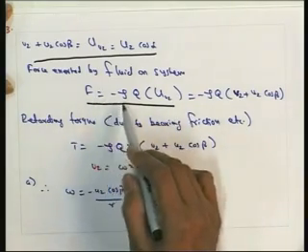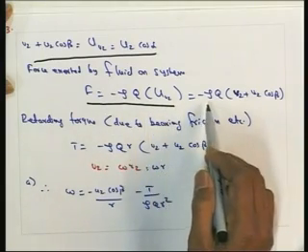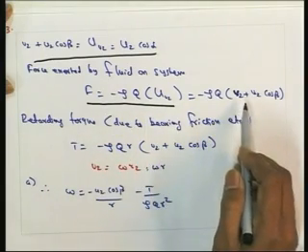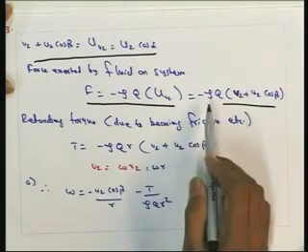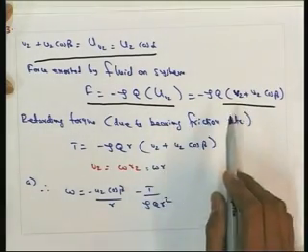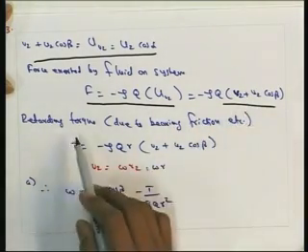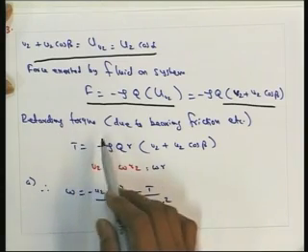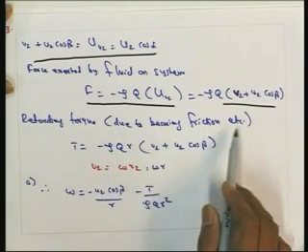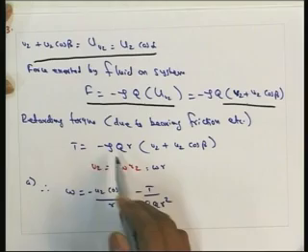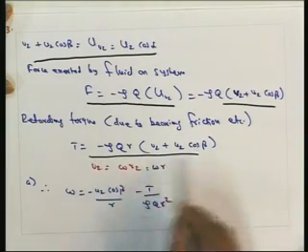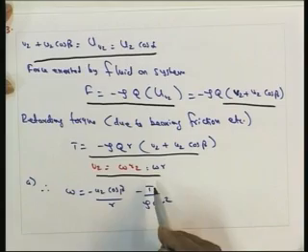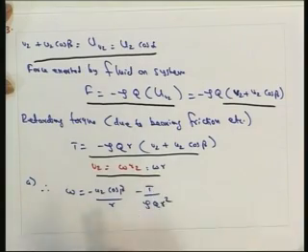So F is equal to minus rho Q into (V2 plus U2 cos beta), where Q is the discharge and rho is the mass density. Now we can write the retarding torque due to the bearing friction, etc. We can write T is equal to rho Q R into (V2 plus U2 cos beta), where V2 is equal to omega R2, that is equal to omega R.